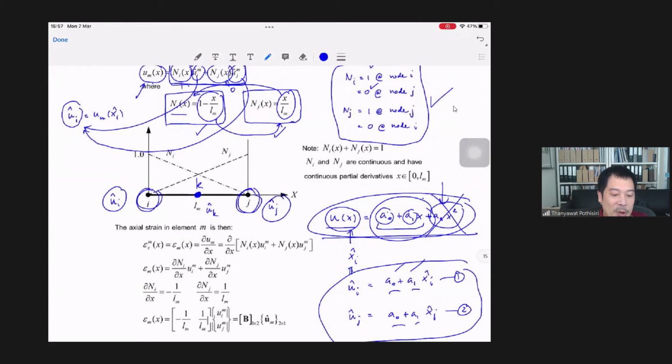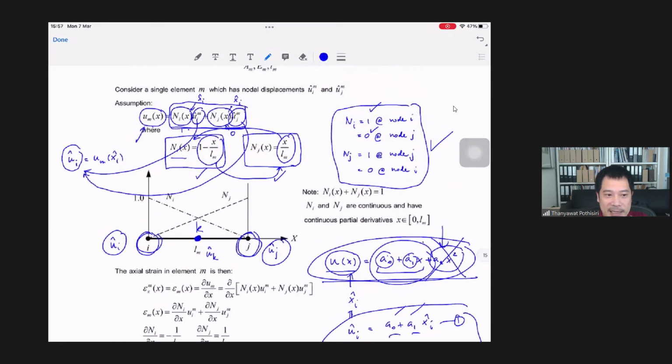All right. So when you pick the number of nodes for your elements, you basically limit yourself with the approximation functions available to you. In this case, you pick a two-node element, so the displacement interpolation function becomes linear functions. And with these properties, you can only have one set of linear functions for your elements.